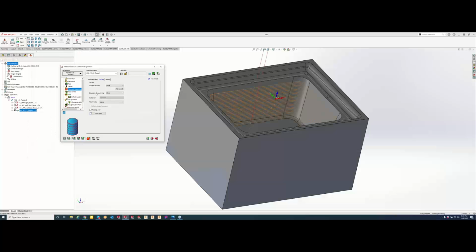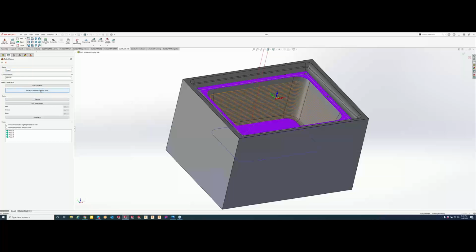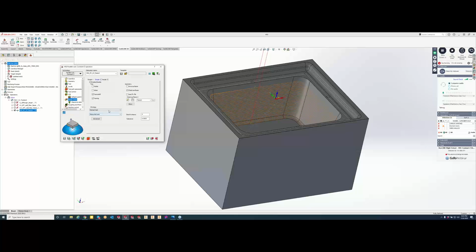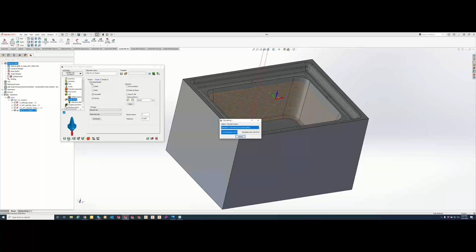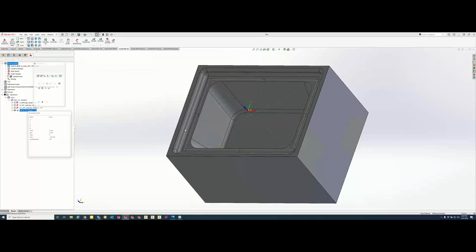So what we'll do is go to our gouge check and we'll enable our drive and I'll uncheck our surfaces, as well as in our gouge 2, I'll turn on our check surfaces and I'll go ahead and grab all those adjacent faces. And I'm going to tell it to retract tool. Save and calculate. Now, when we go ahead and play this through,